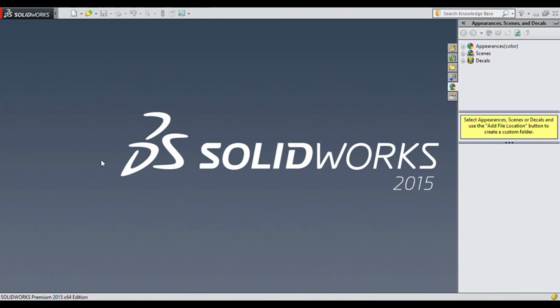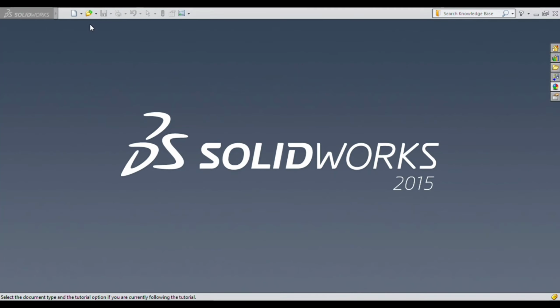So once you click on the SolidWorks icon, the user interface will look like this. I am using SolidWorks 2015 version, but the latest version is up to 2020 also. First we're going to start from the sketch tool. First we move on to how to create a new part. We're going to pick the blank paper like icon, then you will get three modes of drawing components.